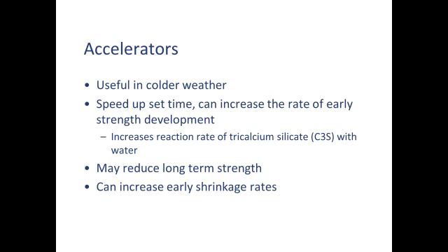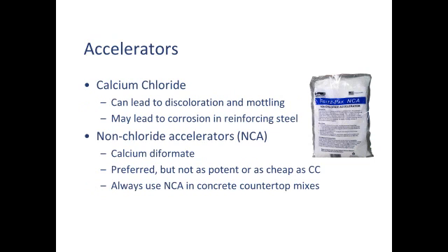Because I'll be honest with you, there isn't a client out there nowadays that is going to wait 28 days for their concrete countertops or whatever you're making. We want to cast them, we want to strip them, we want to get them out the door as fast as possible. So accelerators in general, and I don't necessarily mean chemical accelerators because I'm going to also talk about thermal accelerators, are a way to boost your production rate, to boost your production efficiency by speeding up your early strength gain. What we don't want to do is sacrifice long-term strength, though. That's something nobody wants to do.